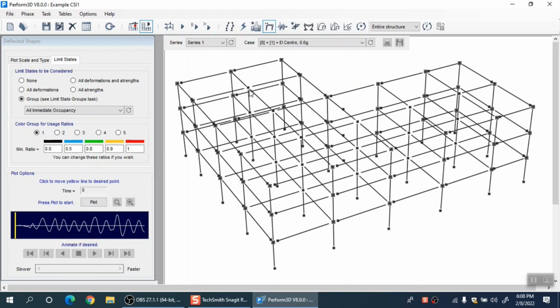So please think in terms of the governing equation of motion, everything will be clear that ultimately all dead load, live load or whatever load, they are going to contribute to your F vector, which is a fixed vector, right. So which means then F is equal to Ku will be solved in static analysis. So no inertial effects, no damping effects will be accounted, right. And if you are going to go for the time history analysis load case, then they can be accounted if the masses are there, right.